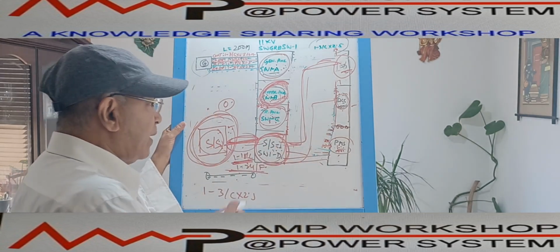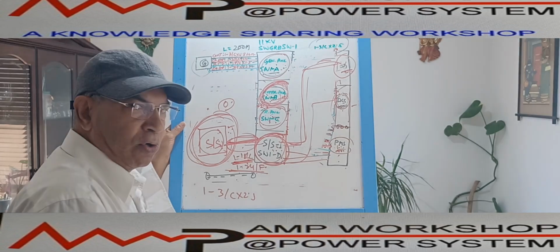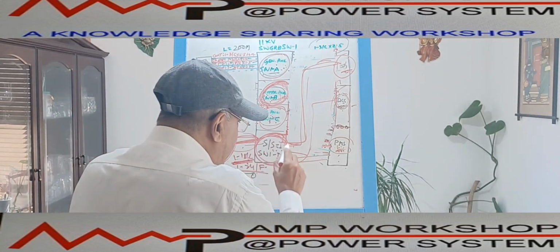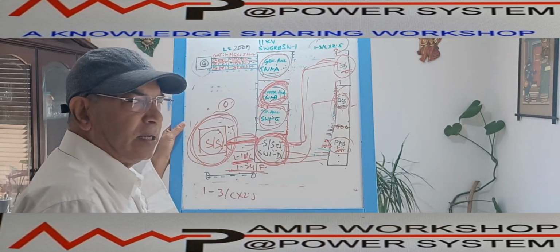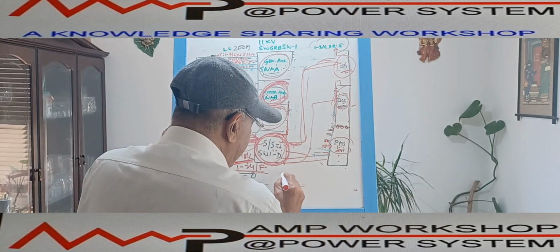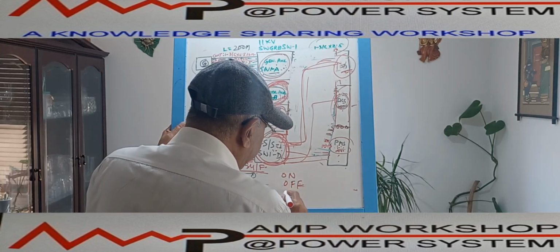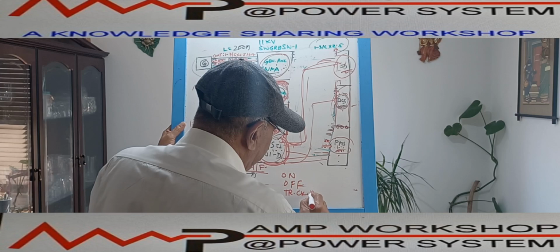That is one thing. Second thing, in the DCS, in the same way, this breaker on and off control as well as various parameters of this panel, that is, various statuses like breaker on, off, etc. As we said, what are the various statuses we have discussed? On, off, then trip circuit healthy, we have seen that healthy signal.